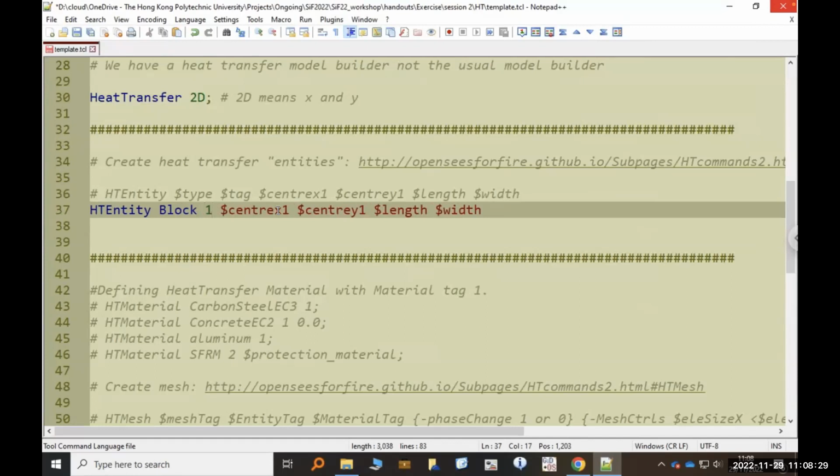The next thing we find is that you have to tell OpenSees where you want the center of your block to be. And this is super useful. Why? Because if you want to construct a more complicated shape, let's say you have 3 materials and they're all a bunch of blocks following each other, you make sure that you place these blocks in the right location so that their faces match, so you can connect them together.